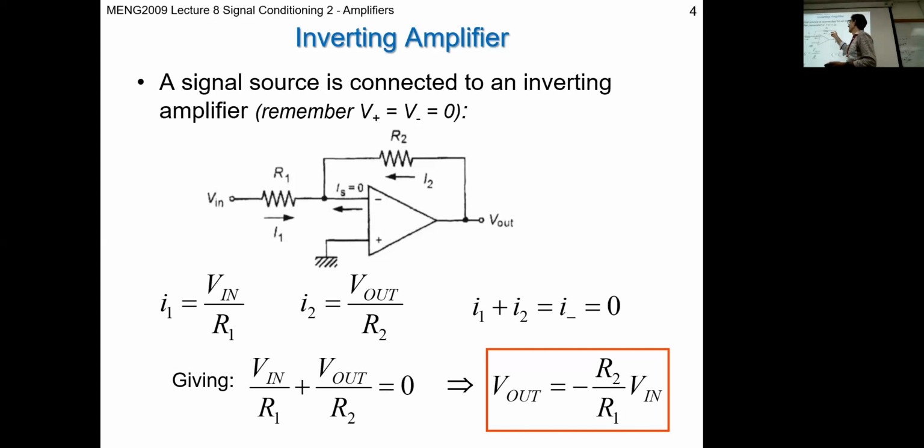It's going to be 0.25 of a watt, because if this is twice the resistance, your current will be half. Half squared is a quarter, so it's a quarter of a watt. But still, that kind of level of power on a resistor is going to cause some significant heating.